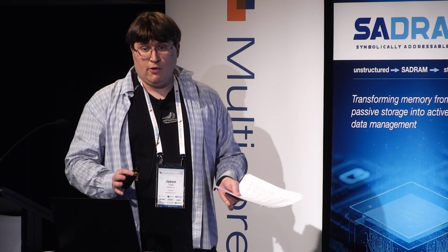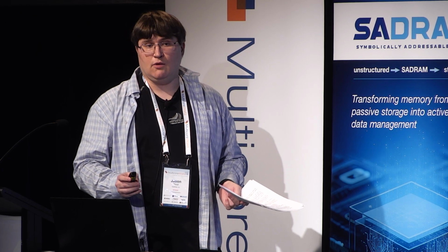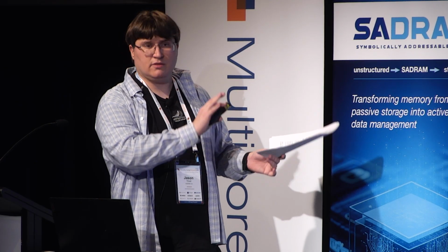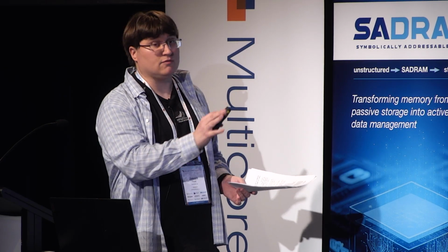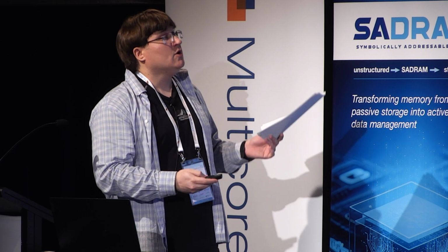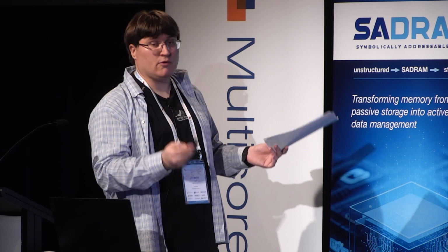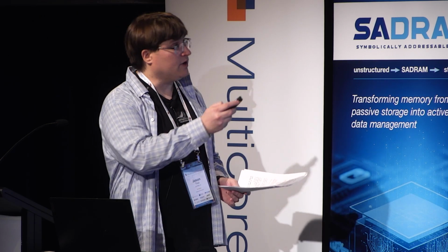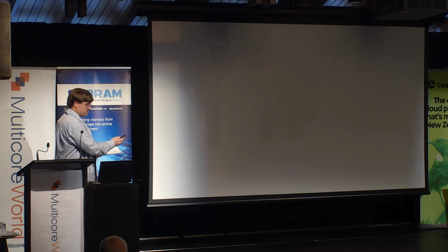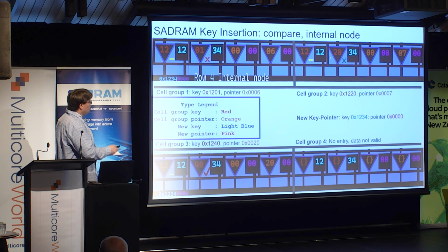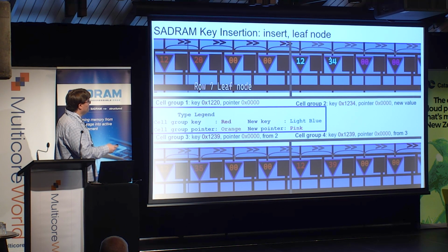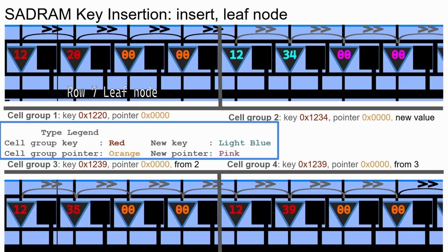All right. So traversing to a different node means we have to close the row. This is all the free computation we can get on this row, just traversing a node. We have to open the next row in order to continue. So we're going to open row 7, and here's row 7. We're going to do a comparison that's similar to the comparison that we just did, and we're going to find the edge, and then we're going to insert the new data into this row.